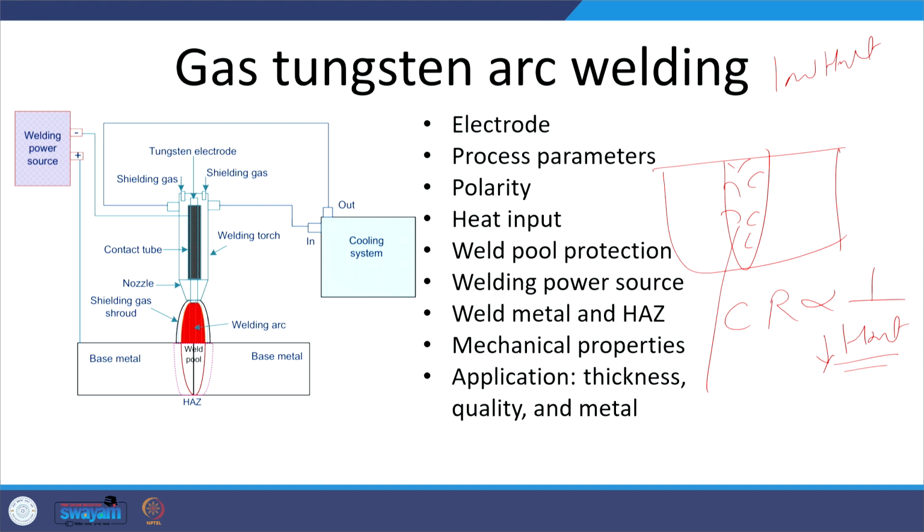If the cooling rate is high, certainly it will produce a fine grained structure, but it will also reduce the time for solidification, meaning the gas and inclusion entrapment tendency will increase, although with GTAW this possibility is very less.